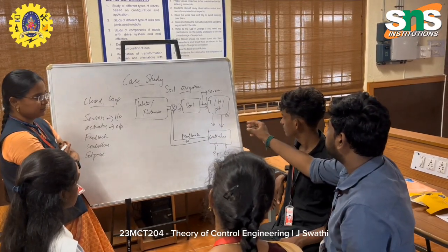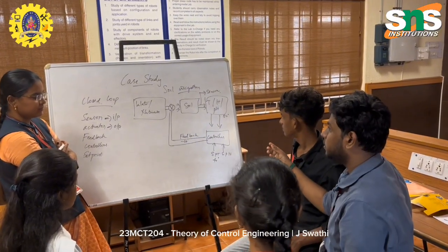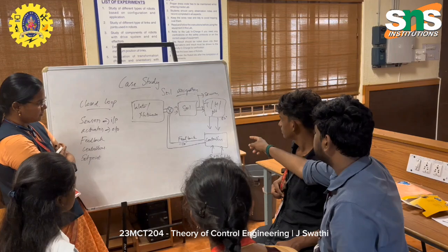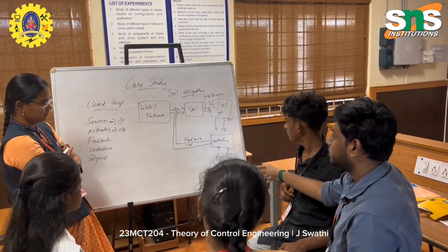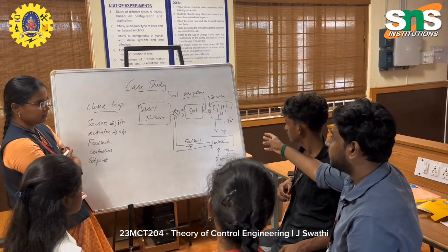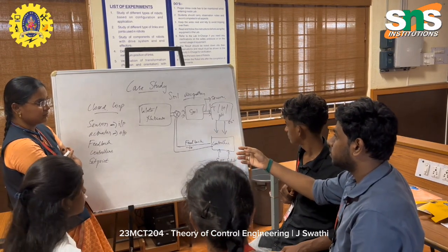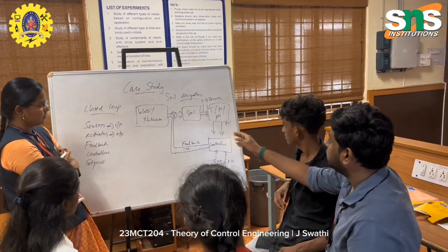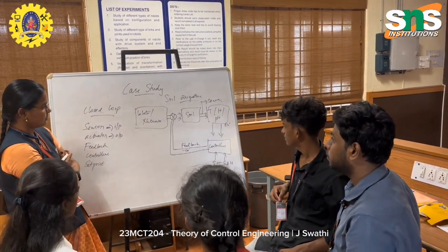To get the signals, we are using sensors to keep on regulating and maintaining the soil moisture. By getting the signals, we give that signal to the controller. In that controller, we will have a set point of 40 degrees. If the received signal is 50 degrees, then the feedback signal is that it should cool down the soil, so it sends the signal minus 10 degrees. From that it goes to the actuators, which send some water and cool down the soil.